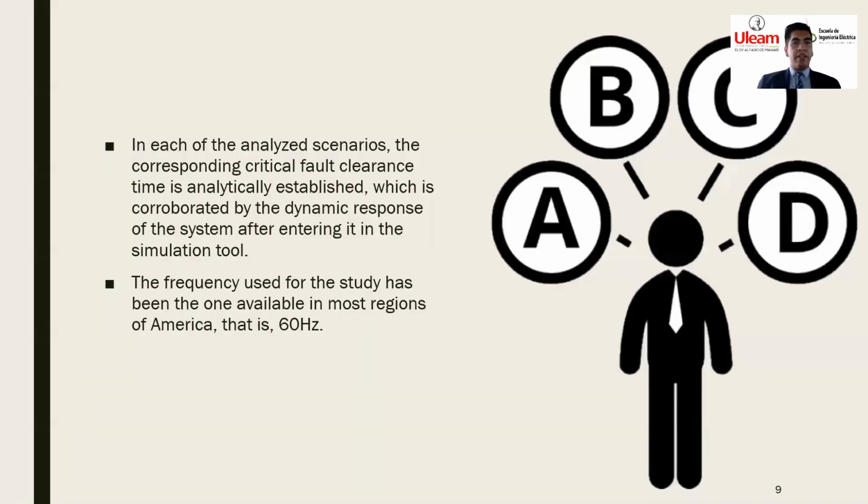In each one of the analyzed scenarios, the corresponding critical fault clearance time is analytically established, which is corroborated by the dynamic response of the system after entering it in the simulation tool. The frequency used for the study has been the one available in most regions of America, that is 60 Hz.